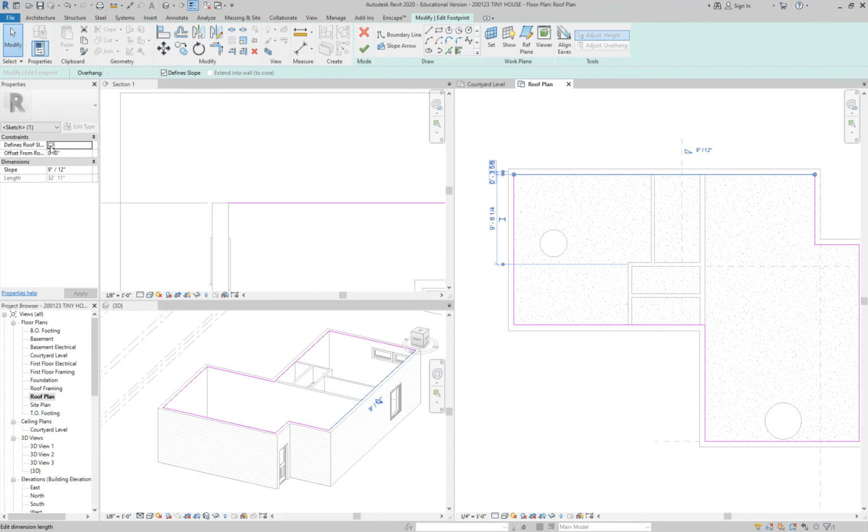Yeah, I did that the first day too. Then come over here and turn off the slope, hit the green check, and then AL, and then click the two lines that you want to touch, and it worked for me. There you go. That worked. So basically the ceiling line and then the roof. Okay. Thank you. And the bottom of the roof?